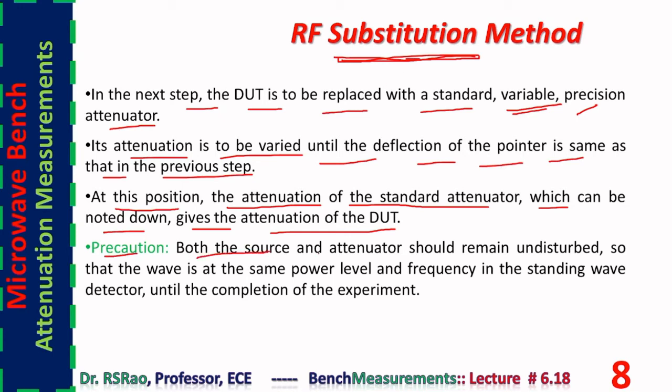Precaution: both the source and attenuator should remain undisturbed so that the wave is at the same power level and frequency in the standing wave detector until the completion of the experiment.